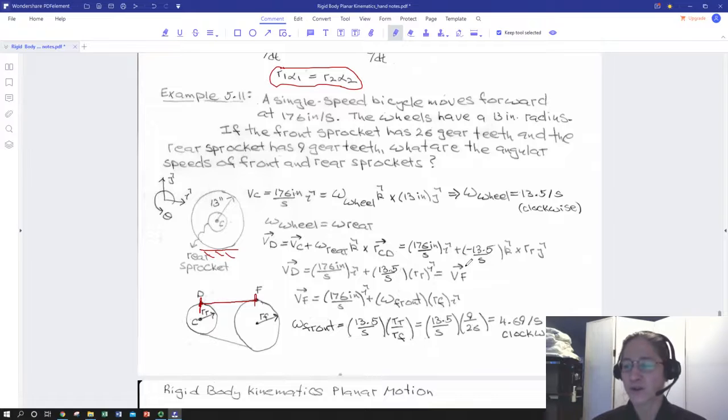And the only tricks are going between a fixed rolling surface and then a curved surface where we have to pull out our tan normal and be careful about not making assumptions about acceleration ever being zero when we have curved surfaces. Just work straight through your equations.